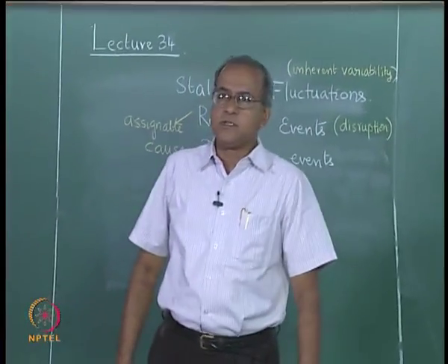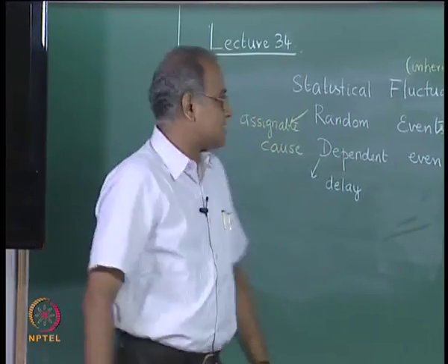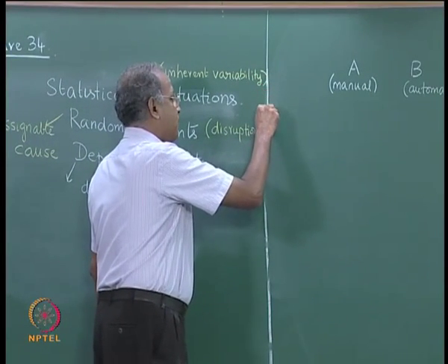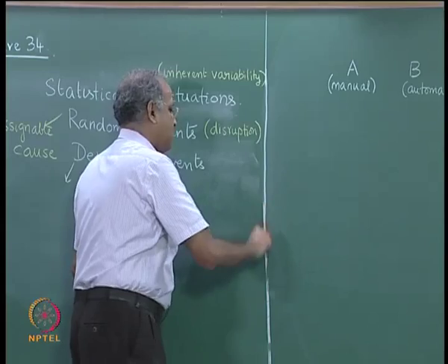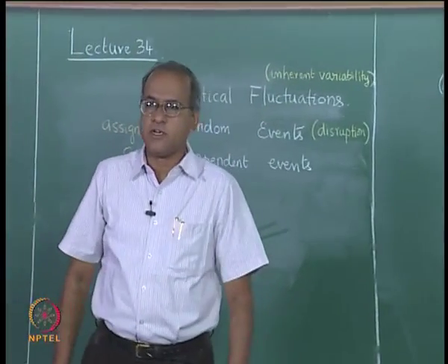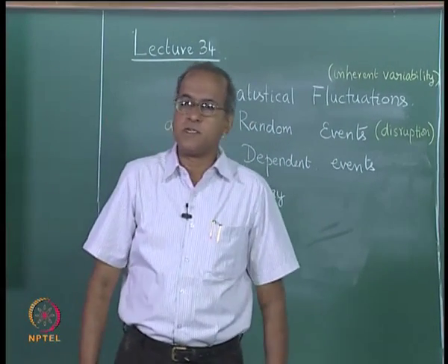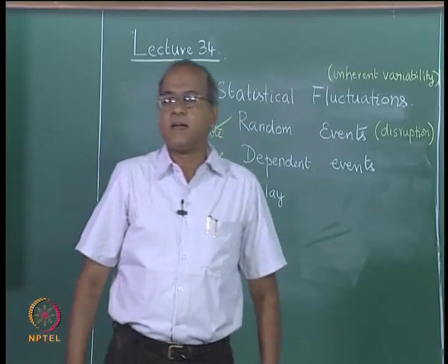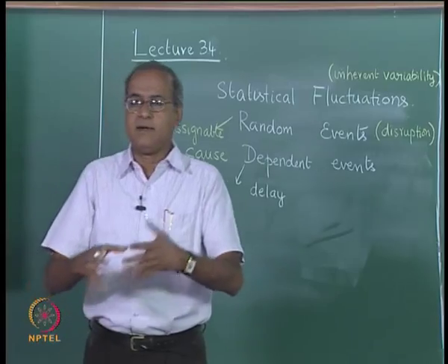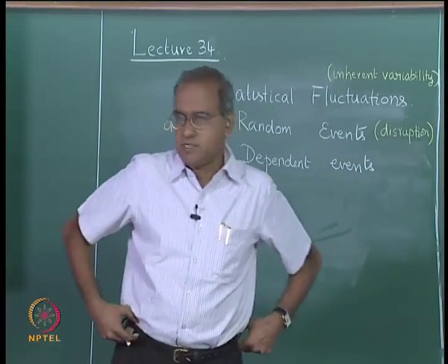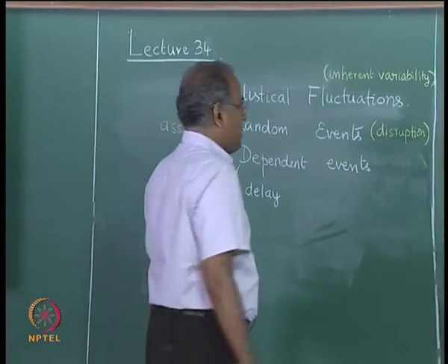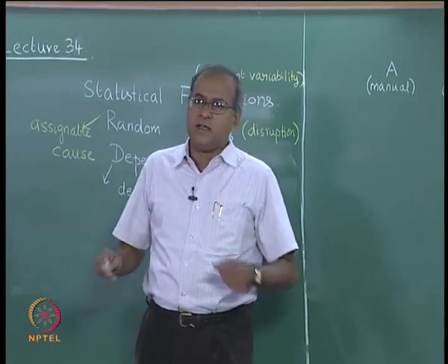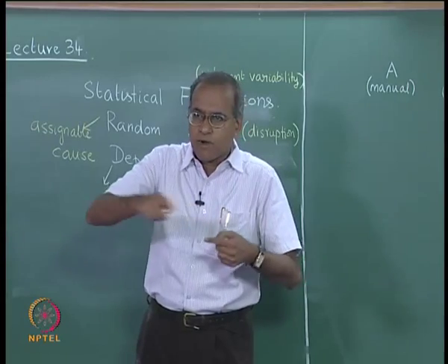Now, we have to produce 100 parts. It is customary to say that A, which can produce at the rate of 25 units per hour, will require 4 hours, while B, which can also produce at 25 per hour, would also require 4 hours. Let us assume for a moment that A and B are physically located close to each other and one piece can move from A to B.